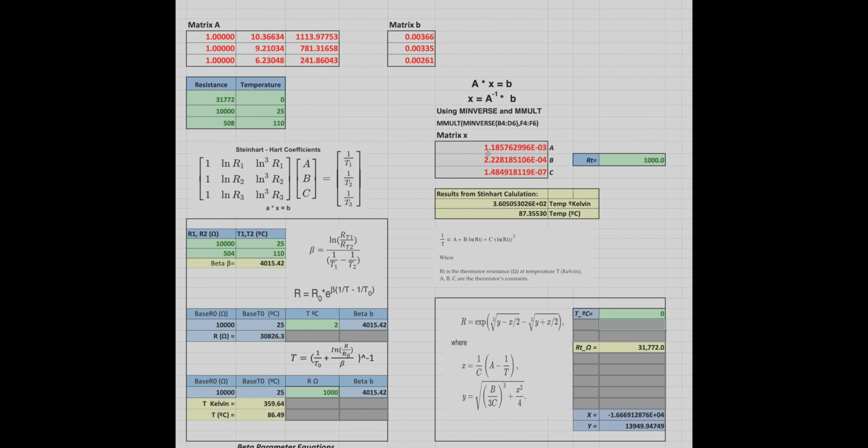Okay, as we move up in temperature, let's take a look at it around room temperature right now. See what it's doing. Our epoxy sensor is almost right on the money. Our Honda temperature sensor is just 0.6 a little high, which could be expected. It takes a little longer, like I said, because it is encased, so it takes a little longer to stabilize, but all in all, that's a pretty good reading for both sensors. Now we'll take a look at it around the 50 C mark, as it stabilizes around 52.